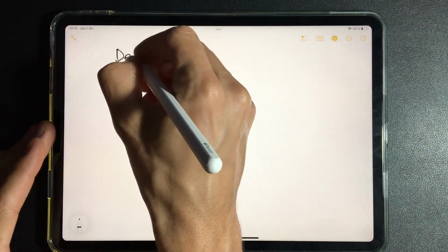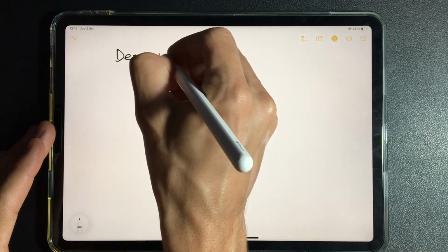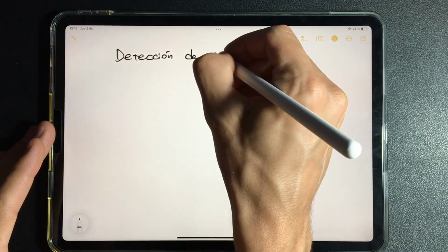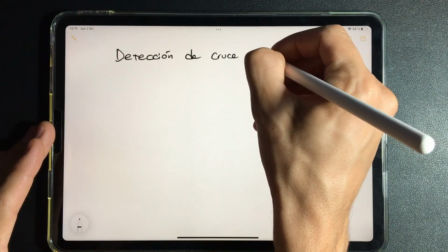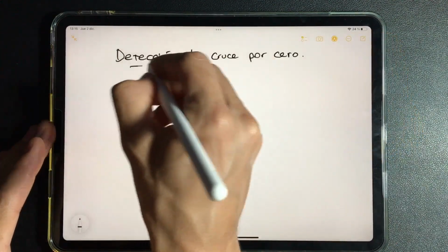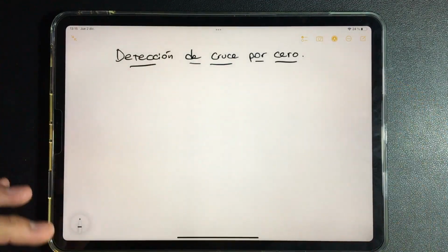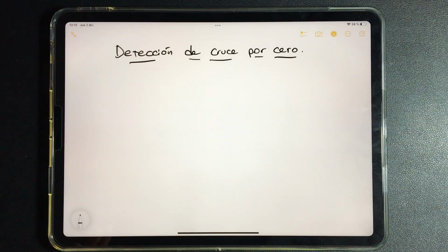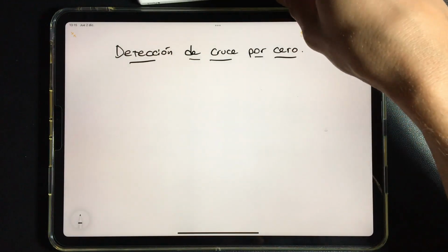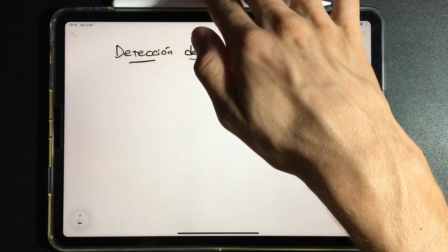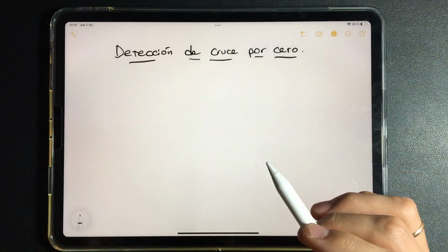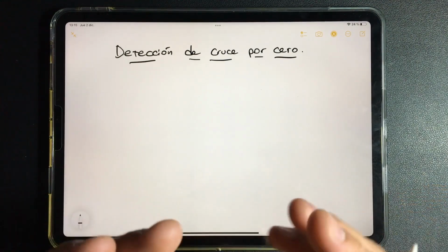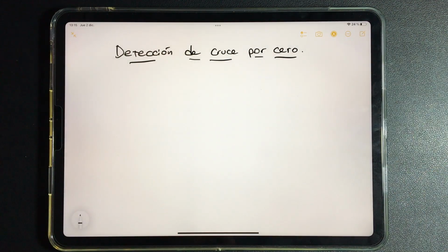With optocouplers, we will be talking about a circuit that is zero crossing detection, a very important circuit in electronic boards. To help you understand what zero crossing detection is, for example, in air conditioning it serves to regulate the speed of the internal fan. When you have that normal AC fan with a blue capacitor on the board or a gray one, this zero crossing detection through an optocoupler serves to identify and make it change its speeds. But when we talk about forced fans, we will be detailing its operation a little more.